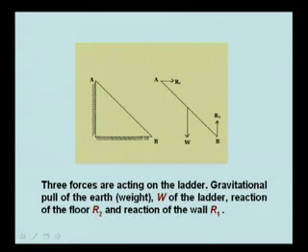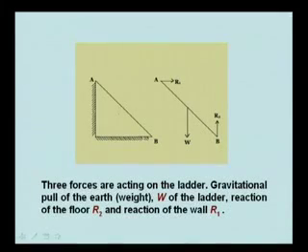I could also have made the free body diagram of half the ladder. That could also have been a free body diagram. Like that we make the free body diagram, and it becomes very easy to analyze what forces are acting. Here I see only the weight, because I am not aware that the floor is putting a reaction here. If the floor puts a reaction here, this also puts an equal and opposite reaction on the floor. So, when we separate that, we only see this R2.